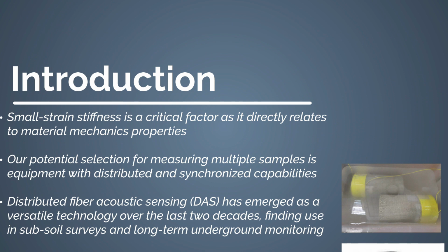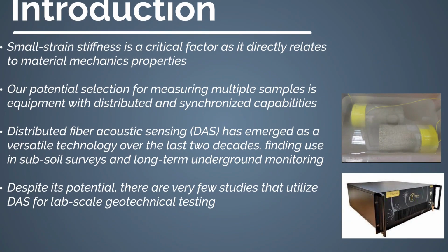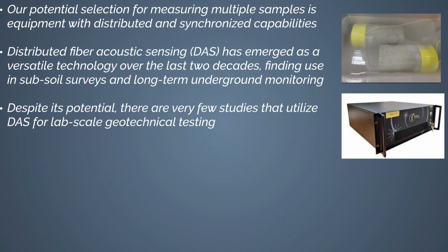Small strain stiffness is a critical factor for cement-treated clay as it's directly related to the material's mechanical properties. Since a large number of samples need to be tested, equipment that can measure multiple samples with distributed and synchronized capabilities is very important. Over the last 2 decades, distributed acoustic sensing, DAS, technology has become increasingly versatile and has been utilized for subsoil surveys and long-term underground monitoring. Despite its potential, there is a significant lack of research on the use of DAS for large-scale geotechnical testing.